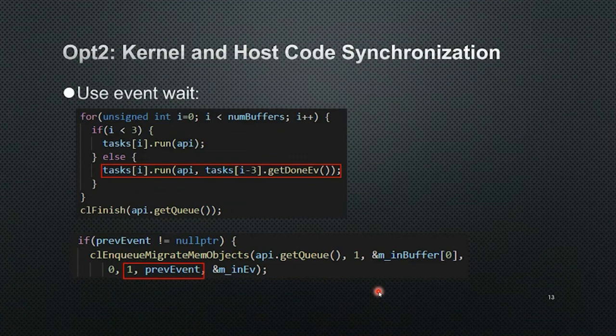That's very much like the total latency, including all the data transfer and the execution of the task. Then we decide the number of outstanding transactions we want to support in order to fully optimize the I/O bus bandwidth.